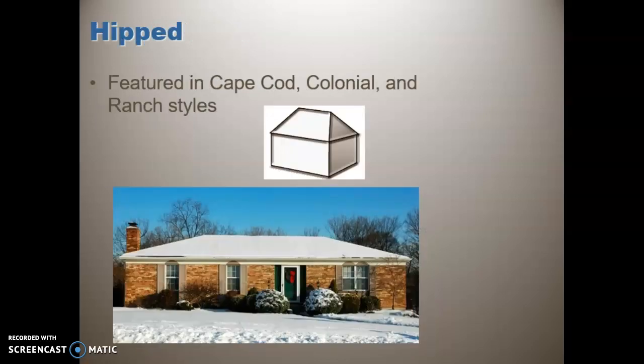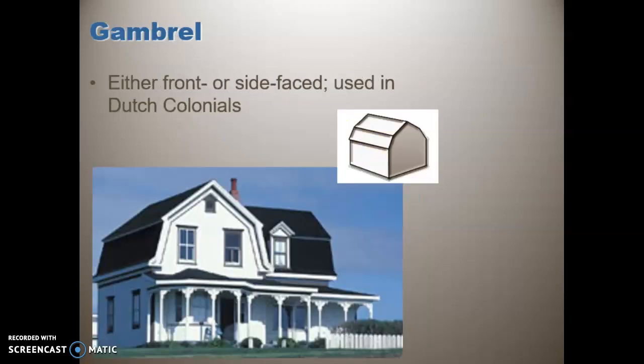Hip roofs, like I talked about a little bit earlier, they shed the wind really well, because any kind of wind or elements that come against the hip roof tend to be parted by the lines of the hip. Gambrel, we don't do too many, nor do you see many gambrels, also known as a barn roof, but it affords you livable space directly under a roof. It also gives you a lot of headroom in there. You can imagine if you did a 7/12 slope, 30-degree angle gable on here, you would hit your head on the corners every time. So gambrel has its place. Also, aesthetics play a big role in it: what type of house, what design.